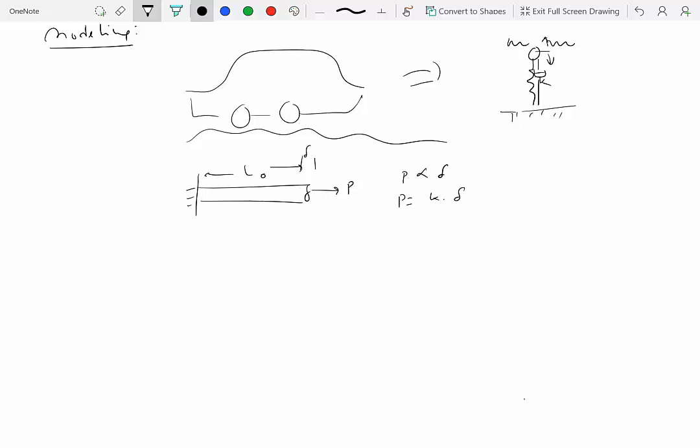So the stretch in the rod is proportional to the force applied, and of course what this constant K would be dependent on is what the length of this rod is, what the diameter is, or the cross-sectional area is, and what kind of material it is made from, right? And the material will basically give you something like elasticity modulus for that, and K would be dependent on all those, right? So this whole thing can be turned now into a spring, right? So you have a spring of spring constant K, which is dependent on elasticity modulus, the cross-sectional area, as well as length.